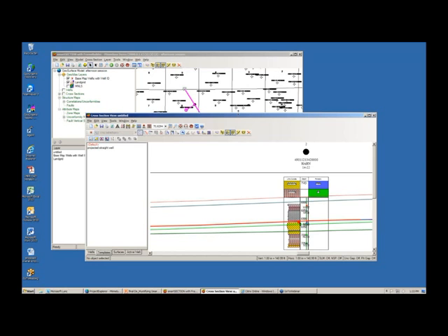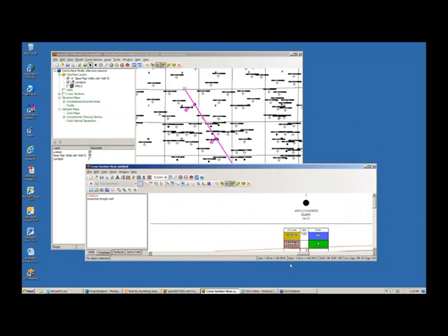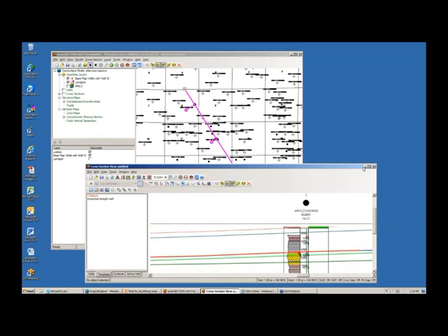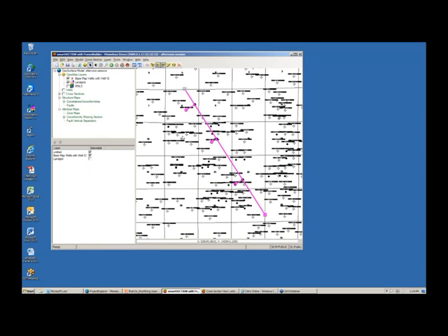The next, more characteristic and typical cross-section that you would want to make is the traditional well-to-well cross-section. I'm just going to go ahead and minimize. I can easily save a cross-section by doing File, Save. Now what I'm going to do is select a traditional well-to-well cross-section. We just come up to Cross-section, Define well-to-well. Your cursor turns into a crosshair, and then we can just click and select various wells that we wish to include. I'm just going to do some kind of east-west. When you're finished, you either double-click or just do a right mouse button and end definition.